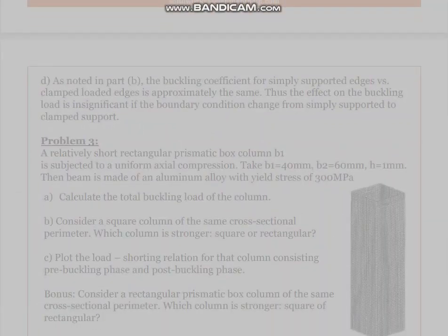D. As noted in part B, the buckling coefficient for simply supported edges versus clamped loaded edges is approximately the same. Thus the effect on the buckling load is insignificant if the boundary condition changes from simply supported to clamped support.